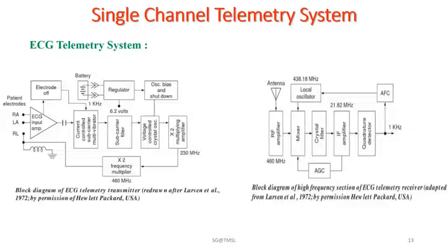Crystal control oscillator circuits must be there, which generate the carrier at 115 megahertz frequency. A class C transistor doubler circuit can be used there. Output power should be maintained at approximately 2 milliwatt.